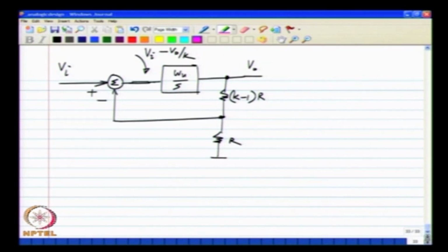So, the negative feedback part is the second part here, which is basically the output of the integrator being fed back to its input. Okay. One of the crucial quantities in the analysis of a negative feedback system is what is known as loop gain. It refers to this: if you inject a certain quantity into the system, let me call it V test, what part of it comes back.